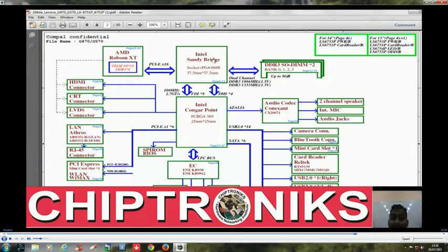So there is a connection between the CPU and PCH, DMI, direct media interface. This is for transferring data between CPU and PCH except the graphic data. I must mention except the graphic data, because for graphic we have FDI, flexible display interface.